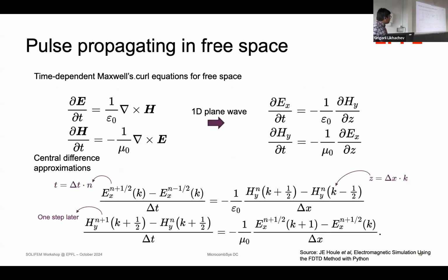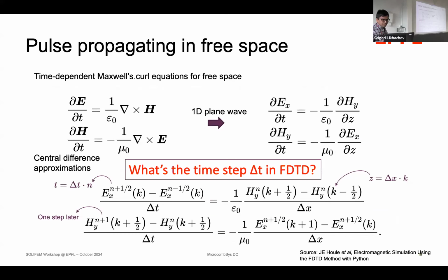So this is the slide that I flashed earlier, but then I didn't get any questions like what would be the time step delta t that you take to solve your differential equations across these E cells. So the time step delta t just depends on the number n that is present over here. When you discretize a system, it basically depends on how many parts of the wavelength you're taking to solve Maxwell's equations on this grid.